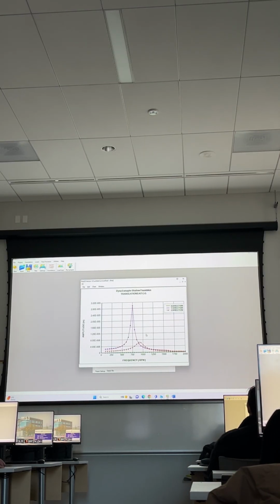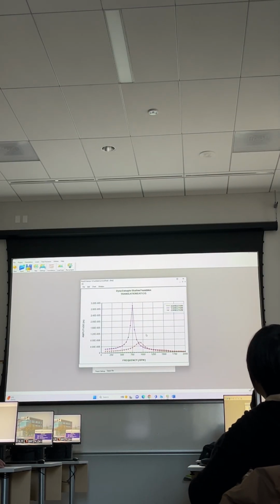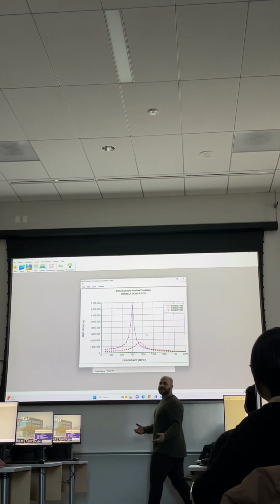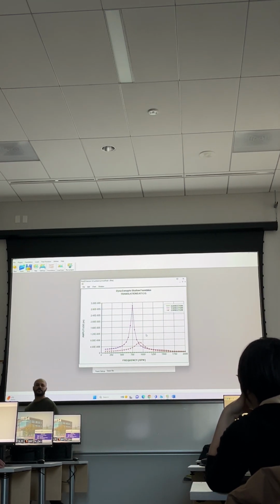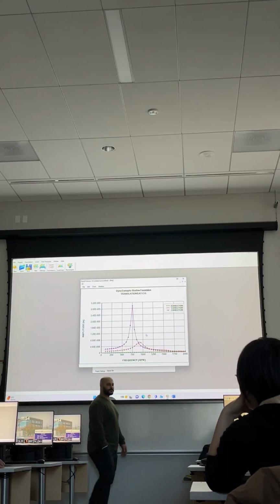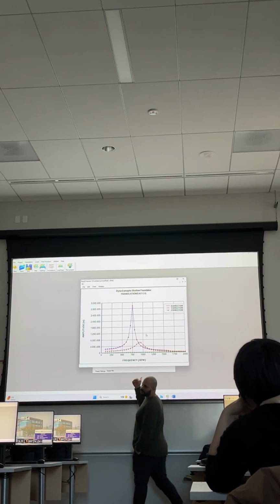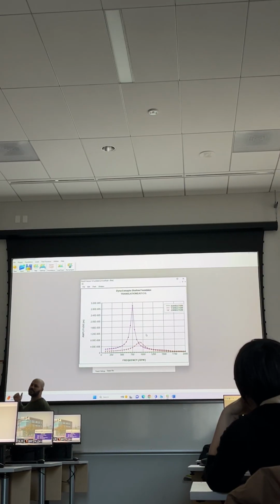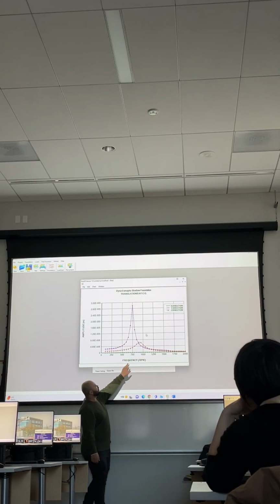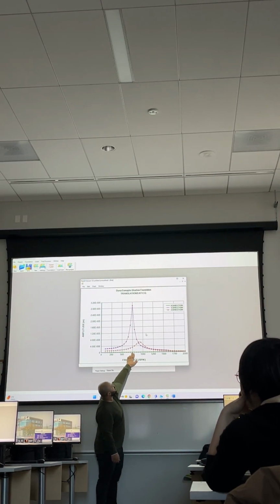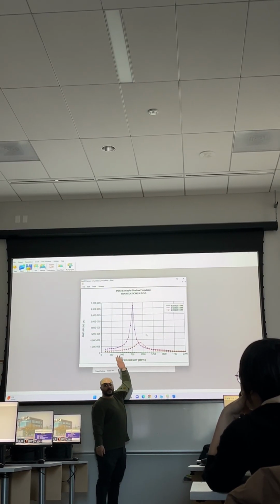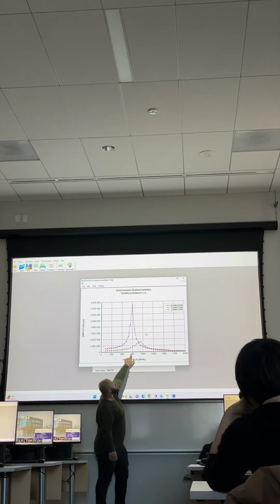So what is the importance of knowing where the natural frequency of the foundation is? If you remember, our machine is working at an operating speed of 900 RPM. Here we have this curve at 775, but imagine if this curve was at 900.